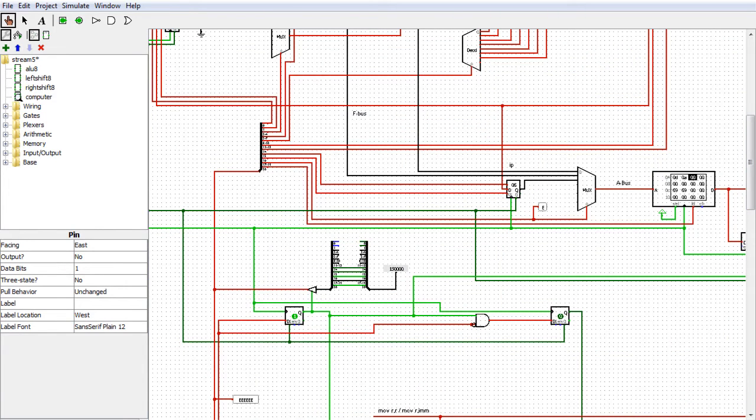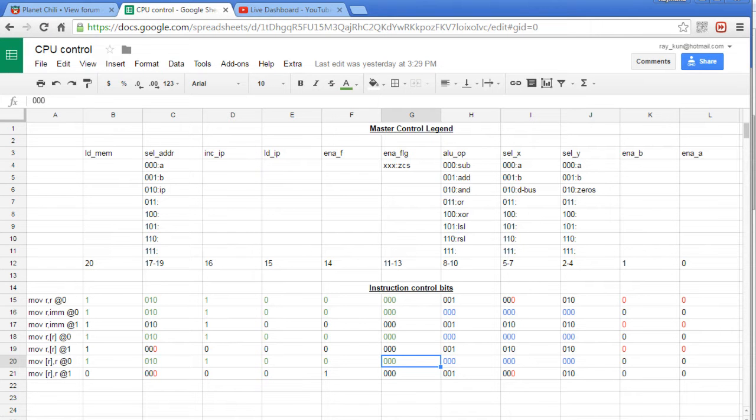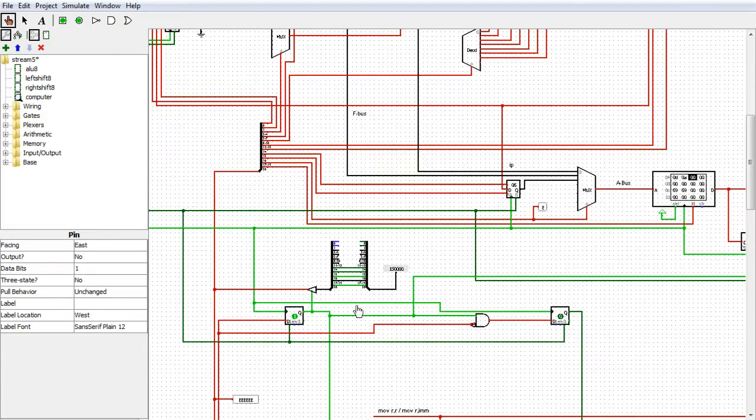Now you might ask yourself, well, why didn't that happen for any of the other instructions? The first two that we did, or 3 depending on how you're counting, they worked fine. And the astute of you might realize that one of these things is not like the others. One of these things doesn't belong. So for all of the instructions previously, we had been setting load memory to 1, which is the same thing that it is set to out of here.